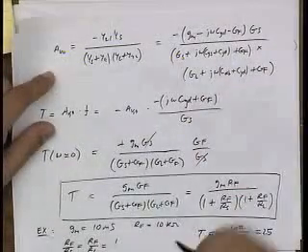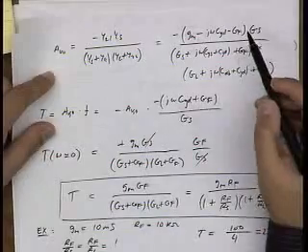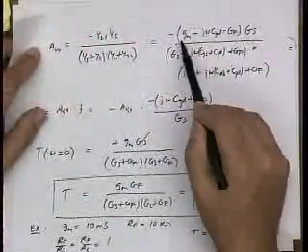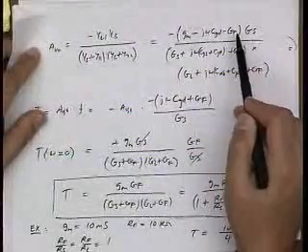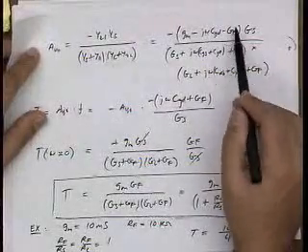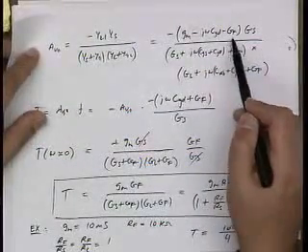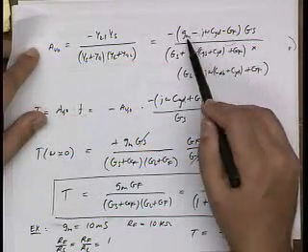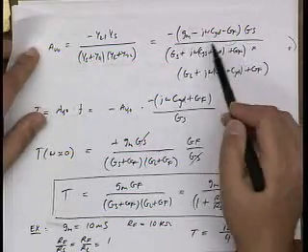If you look at my calculation, for instance, in Y21, when I wrote down Y21 somewhere, I neglected this GF term, right? This is GM minus GF. What's this term? This is the feed-forward term, right? And in fact, you can see the feed-forward term subtracts from my GM.